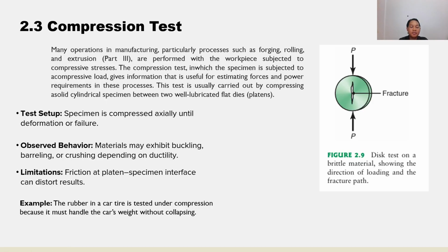Next is the compression test. Many operations in manufacturing, particularly processes such as forging, rolling, and extrusion, are performed with the workpiece subjected to compressive stress. The compression test, in which the specimen is subjected to a compressive load, gives information that is useful for estimating force and power requirements in these processes.